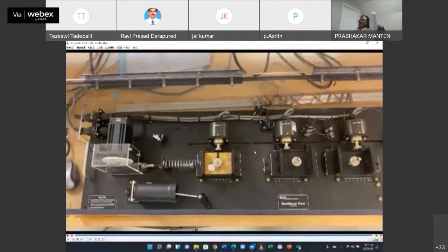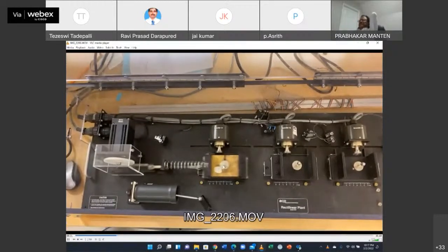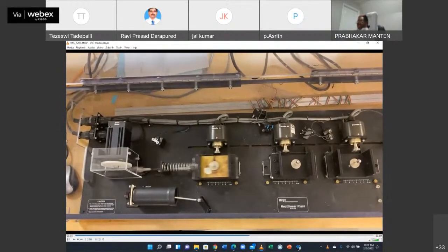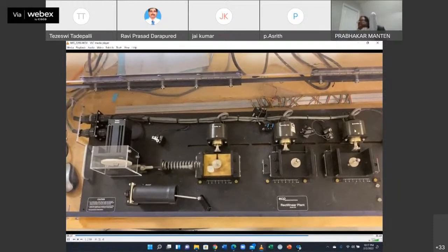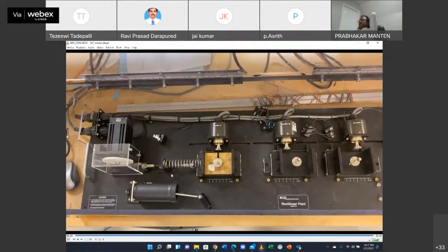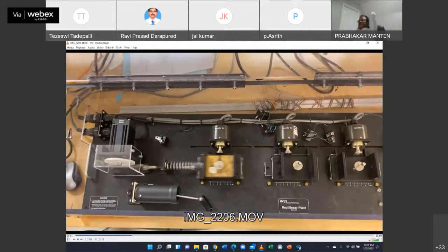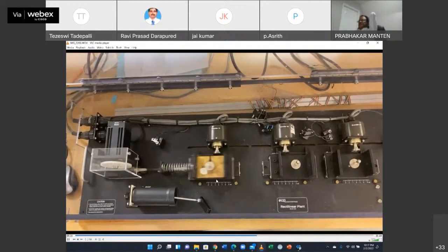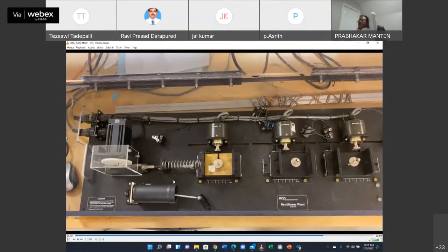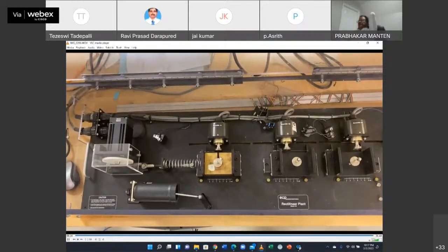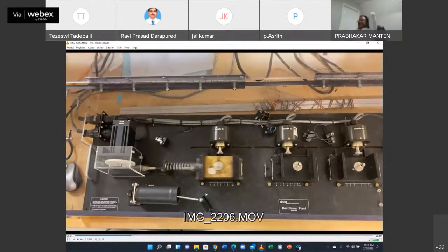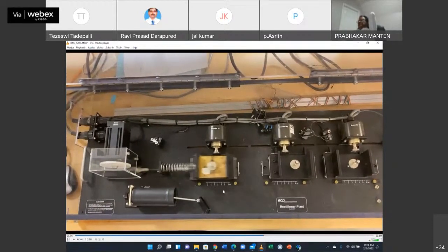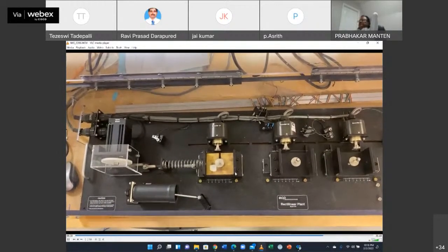You see the spring mass, then they change the spring, they change the mass, they add mass, delete, and study a single degree. Then they attach it to 2 masses, then to 3 masses. Then they add a damper. This is the air damper. There's the air cylinder with a piston inside, and if this is connected in parallel, it acts as a damper. Then they study the effect of the damping and see that the frequency doesn't change, but the peaks shrink a little bit. So this is single degree.